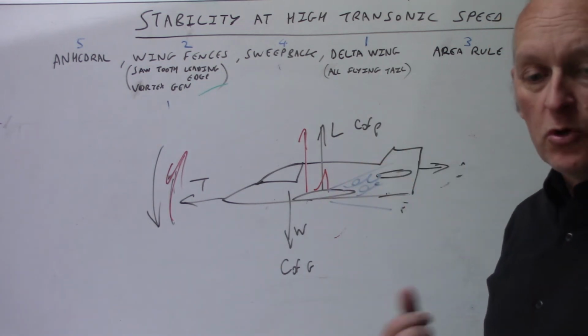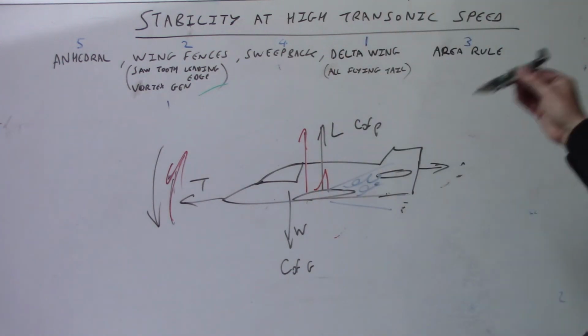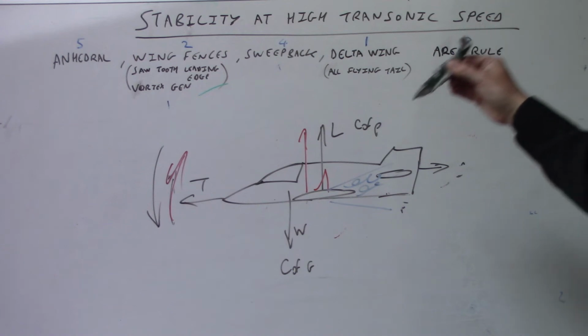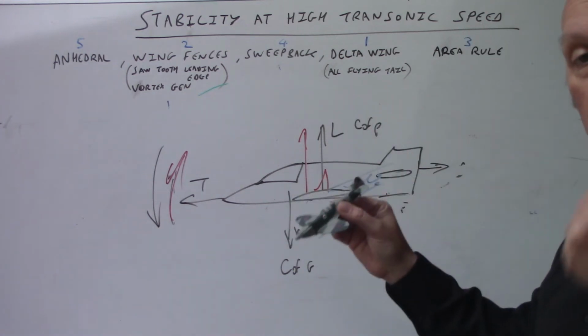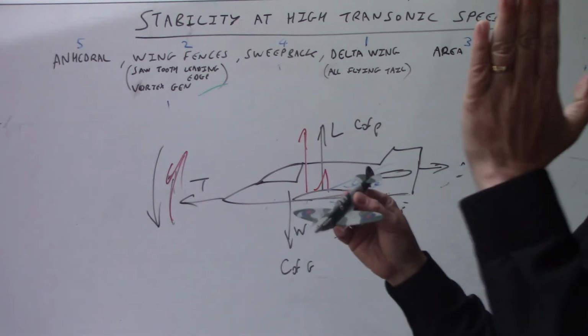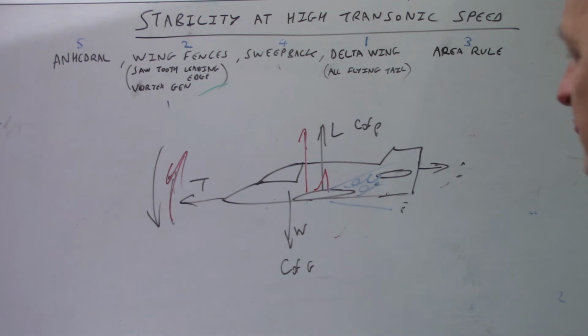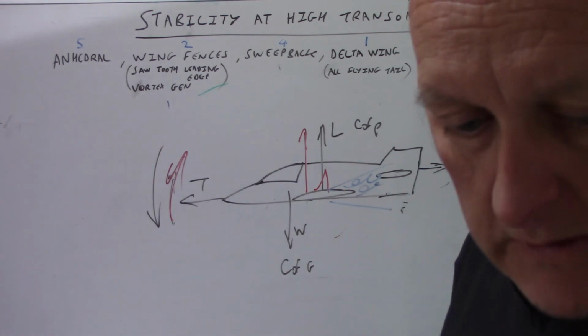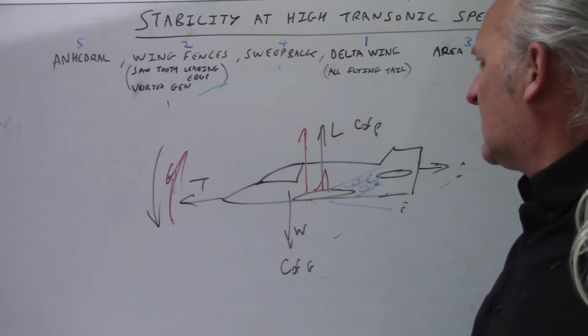What some Spitfire pilots reported was that when that happened, without the downforce on the tail, they got stuck in a nose down death dive that they could not pull out of, because when they pulled back, the elevator was in separated flow. So a control surface in separated flow will not work. Which brings us to ring fences and things like that, and vortex generators.